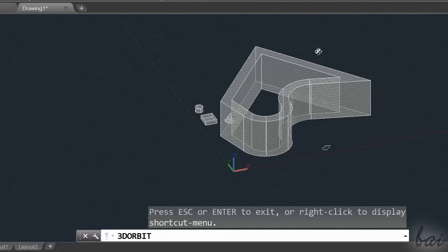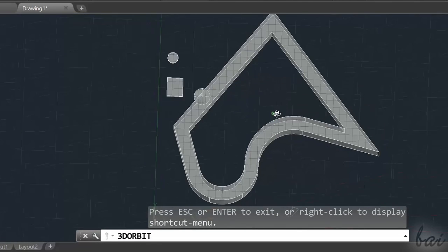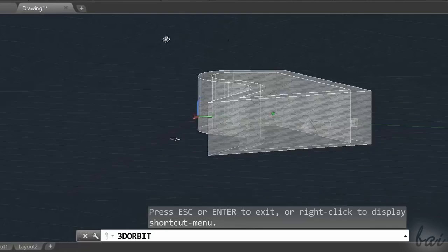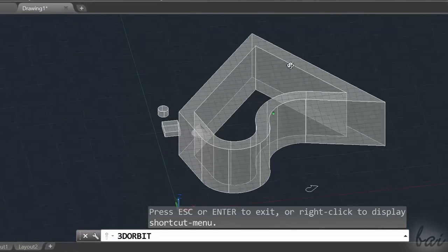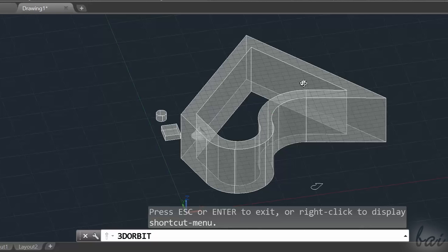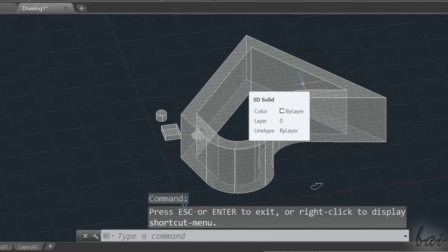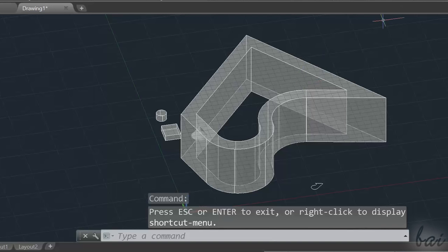Remember that the polysolid base behaves like 2D objects. It always lays on the ground plane or any plane parallel to it. Let's see now how to edit objects in a 3D environment. It is better to use the X-ray view in order to check solids also internally.